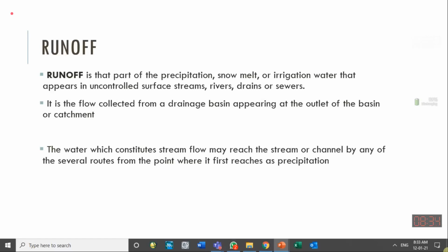Reason I am talking about it is, in last week there was a viva of MSc. A student of MSc was not able to differentiate between these two, and we consider this is a very basic thing. You should be knowing it. So the difference between watershed area and the command area: watershed contributes water at a certain place, while command area is that which is commanded by that location, which is provided water by a certain structure.